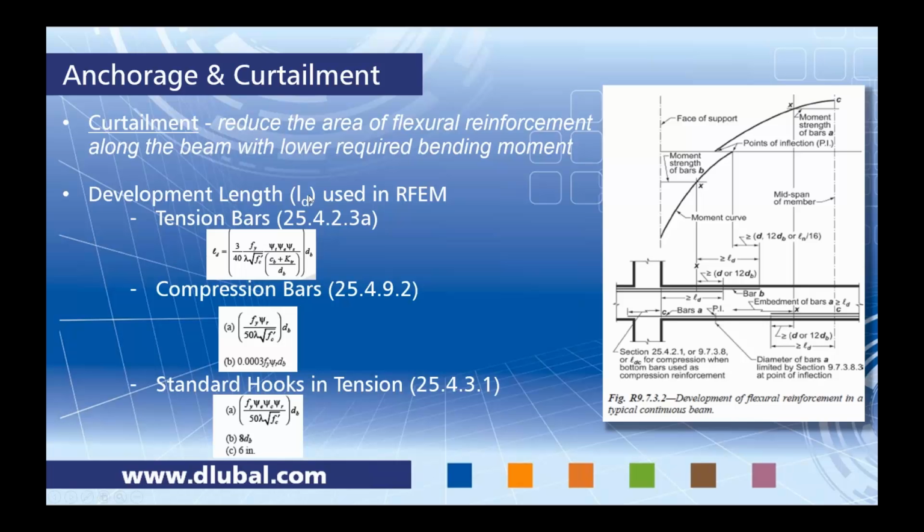The other entry that we need to consider, which RFEM is doing in the background, is the development length. The program knows whether the bars are in tension, compression, or if they're a standard hook in tension, and it will refer to the code, chapter 25, for all of these varying equations to make sure that these development lengths are correctly taken into account.